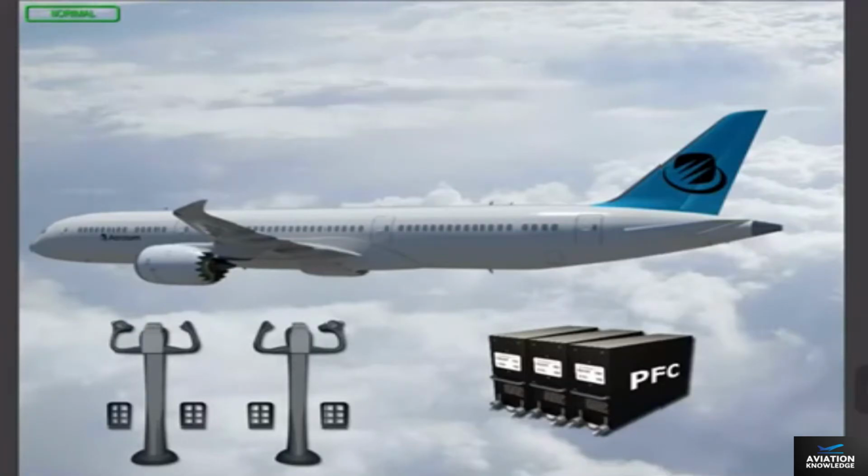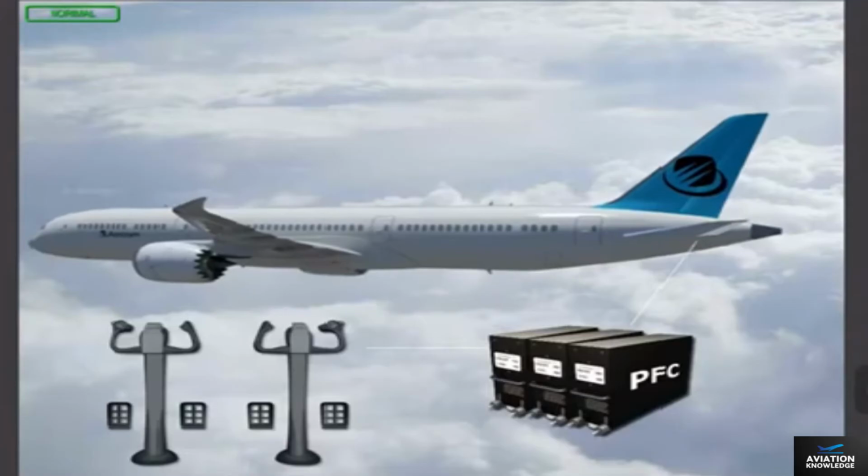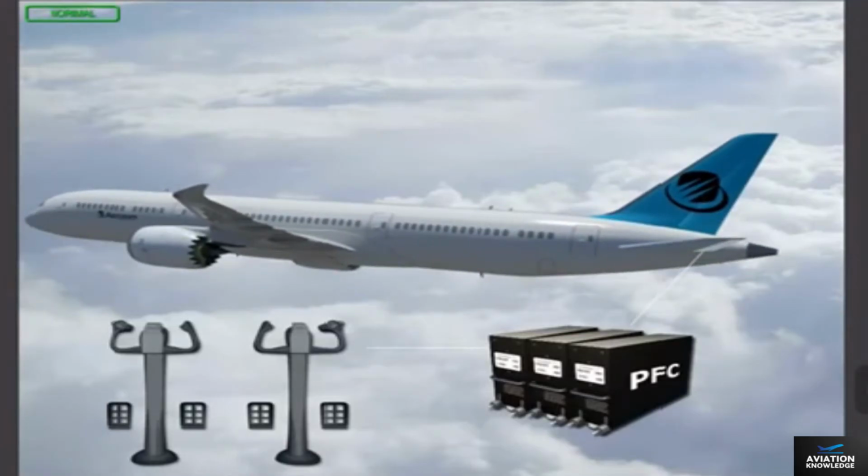When pilot trim inputs are made, the PFCs automatically move the elevators to achieve the trim change before moving the stabilizer, which streamlines the elevator. Stabilizer motion may also automatically occur to streamline the stabilizer and elevator for thrust and configuration changes. Once the control column forces are trimmed to zero, the airplane maintains a constant speed with no column inputs. Thrust changes result in a relatively constant indicated airspeed, climb or descent, with no trim inputs needed unless airspeed changes.